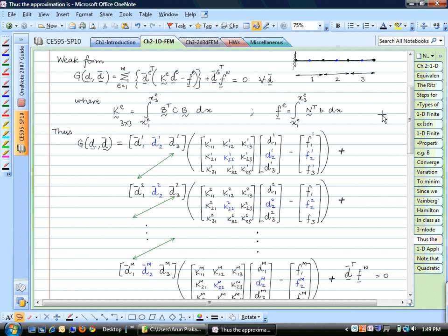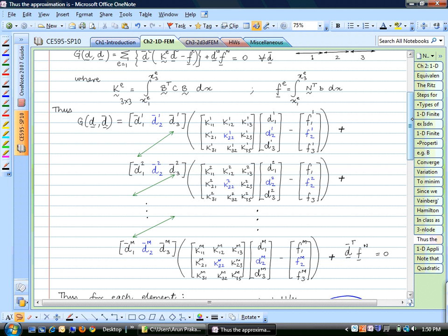And you can imagine that if you have a finite element mesh that is maybe thousands or millions of degrees of freedom, then a 50% increase in the size of your stiffness matrix is not going to be good. So in this particular case, there is a very neat way of rearranging our equations such that we end up with the same size of global stiffness matrix that we had before. And so let's take a look at this.